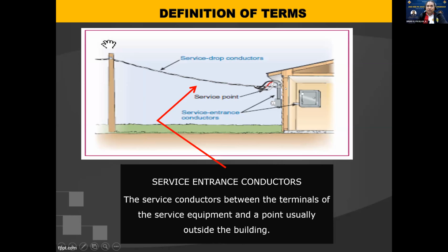So we all know that if it's in free air, yung conductors natin can carry much more capacity than doon sa indoor, no? Yung enclosed na conductors. So for the same cross-sectional area, mas malaki ang capacity nitong nasa free air, no? By I think almost two times.